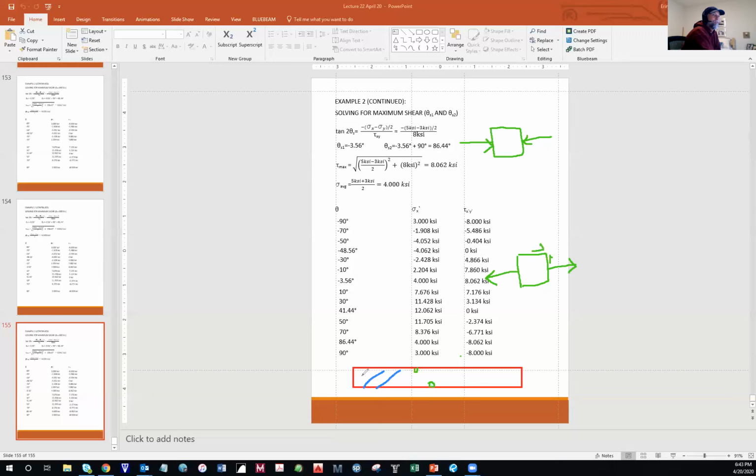But if I pull a cube over here towards the end and in the middle, then that cube towards the end is going to have big shear on it, and basically no normal stress because it's at the center of gravity. So My over I is 0, and it might have a little compression on the cube from the loads making their way down into the bearing here. So I hope I'm answering your question.